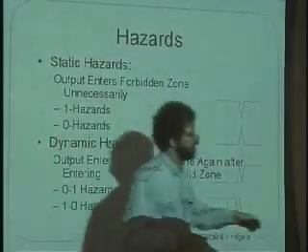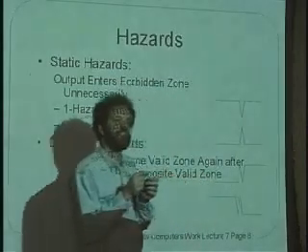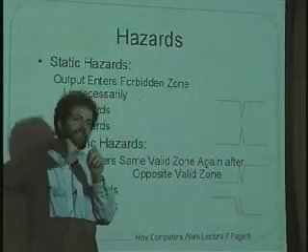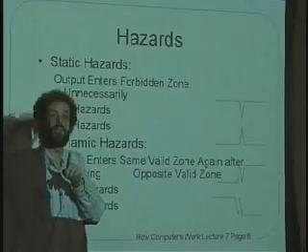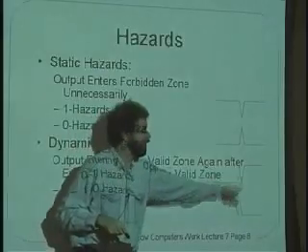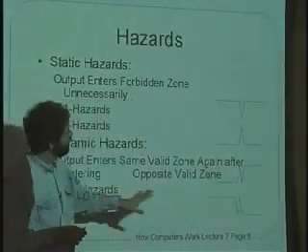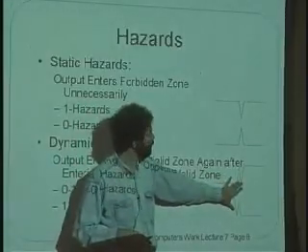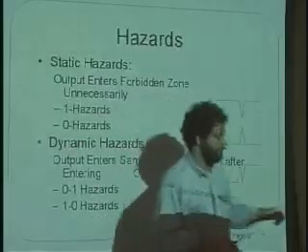Like, you know, there's a set button here to set the minute and the hour, and if the switch has a little bit of dirt in it, right, then the clock suddenly jumps a whole bunch, right, because the set button has kind of gone up and down many times in order to, you know, increment something. That would be a hazard that's kind of like this, okay? We're going to talk about why these things don't matter in general and why these things can't happen, but we are going to address these 1-1 hazards.